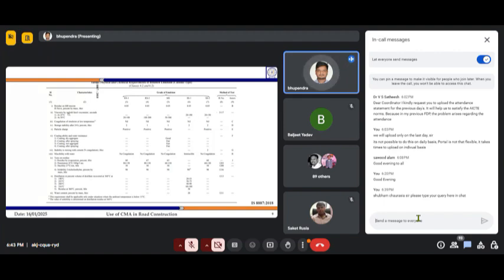Okay, so viscosity is checked using the IS 3117 code, and viscosity is checked at two temperatures. For RS 1, RS 2, and for medium setting, viscosity is checked at 50 degrees Celsius, because their viscosity is high at 25 degrees Celsius. So these values are given. You check the viscosity using the Saybolt Furol viscometer, and the viscosity is in seconds.